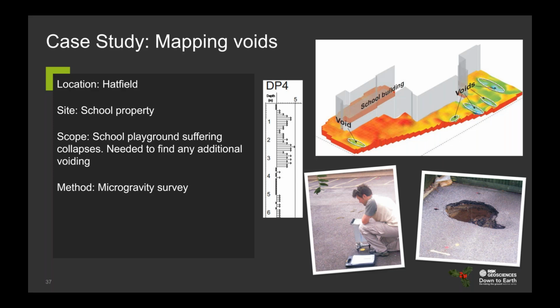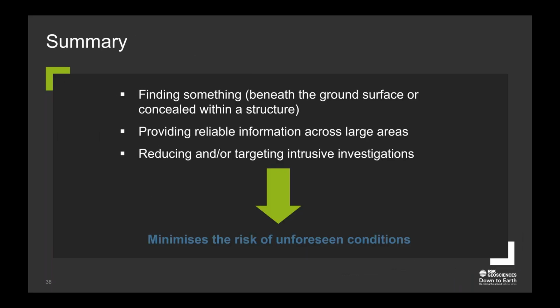in that location. These sorts of voids can be common in areas where there are things like limestone bedrock, for example. And in this case, they were able to easily target and then grout up the holes, which then made the playground safe so that the kids could return to school.